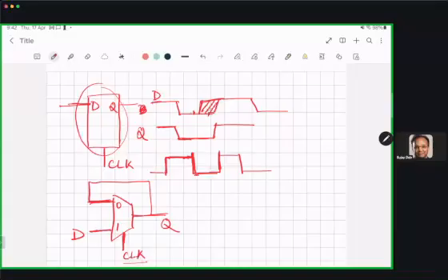So the question was, will this work if I connect it like this? Let's say Q is currently 1 and then the clock went low. Will it remain 1 till the next positive level comes? The output goes to the zero input, and we are assuming that it will stay there. I don't know if it will stay.